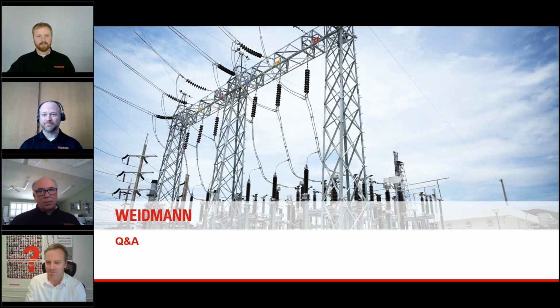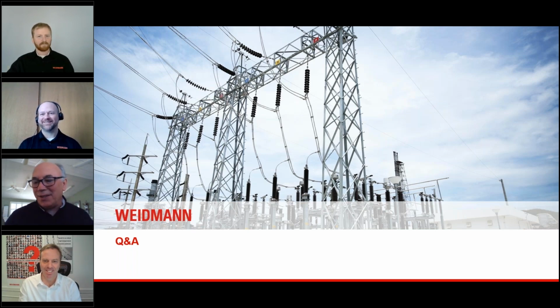Thanks, Jason. How prevalent is methanol assessment with regards to determining paper life expectancy? I'll take that one. If you're looking at a transformer that's in service, we try to measure the insulation life by the degree of polymerization that I described earlier. The challenge is that with a transformer in service, you're not able to get a sample of the paper press board from the location that you want to test to do this viscosity measurement.